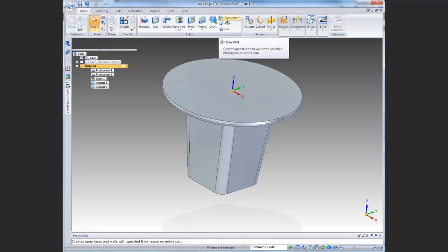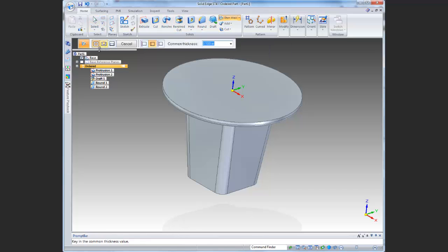It's called thin wall. What thin wall lets you do, there are kind of 3 steps. You define the thickness, and then you decide which face is going to get removed. So this face in the bottom is going to get removed, and then it'll do it. So first, the thickness. For the parts that we use, we'll typically use, like, I don't know, 50 thousandths to 70 thousandths is a common thickness we'll use, 70 being kind of the most common. For this, we're not going to really machine it anyway, so I'm going to use 100 thousandths.